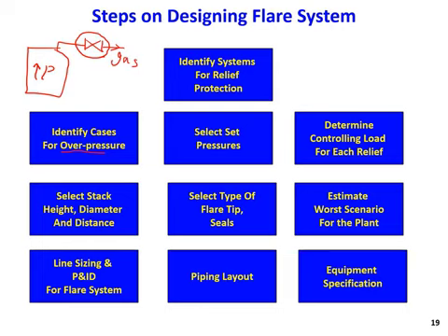So how do we design the set pressure of this valve? Let's say the maximum pressure that this vessel can tolerate is 100 bars, so the set pressure of this valve can be, let's say, 80 bars. The operating pressure of the reactor is usually, let's say, 30 bars or even more. It can be 50 bars.